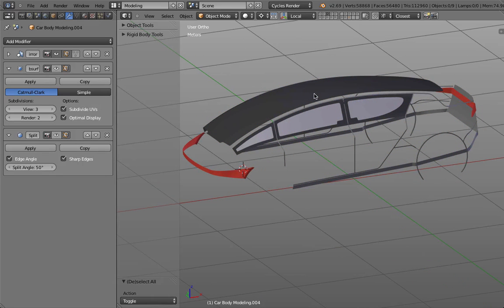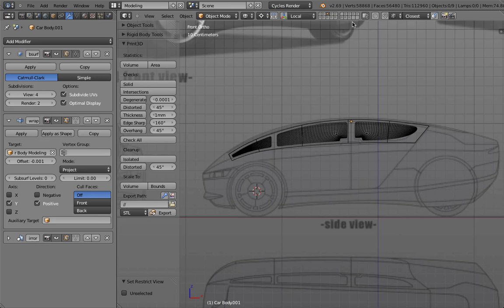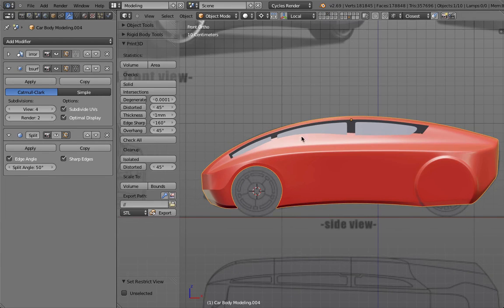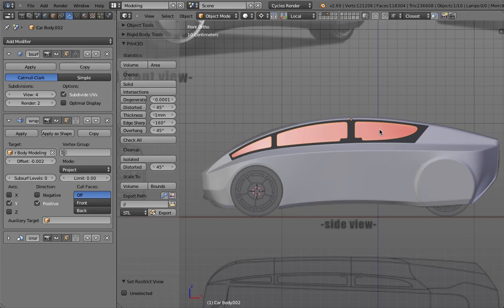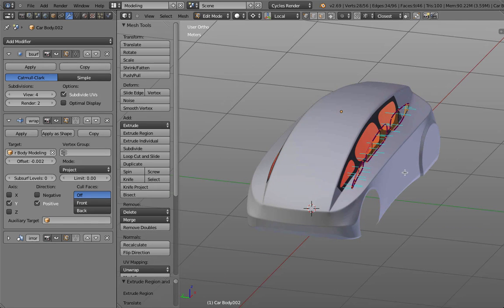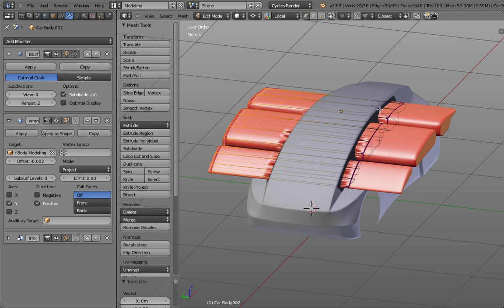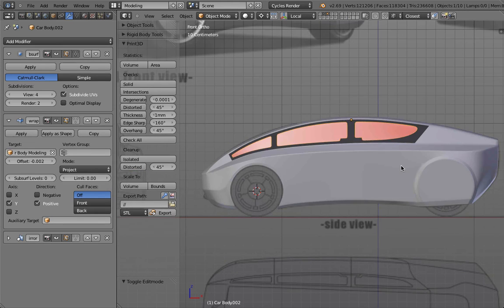So there are now multiple ways how we can do this. And let me select all those, press I and H. So I have here, for example, my car body in the back. Oops, wrong one. Still projecting on this one. And I would like those windows to cut out. Now, I modeled those by hand, and there are multiple ways now how I can easily, for example, cut everything out. The easiest way would be to create, for example, a cylinder that penetrates completely through it, so I can cut everything out. Same with here, but again, I'm using edge creasing to a certain degree, so I'm going to run into some problems here, but that's not really a problem.